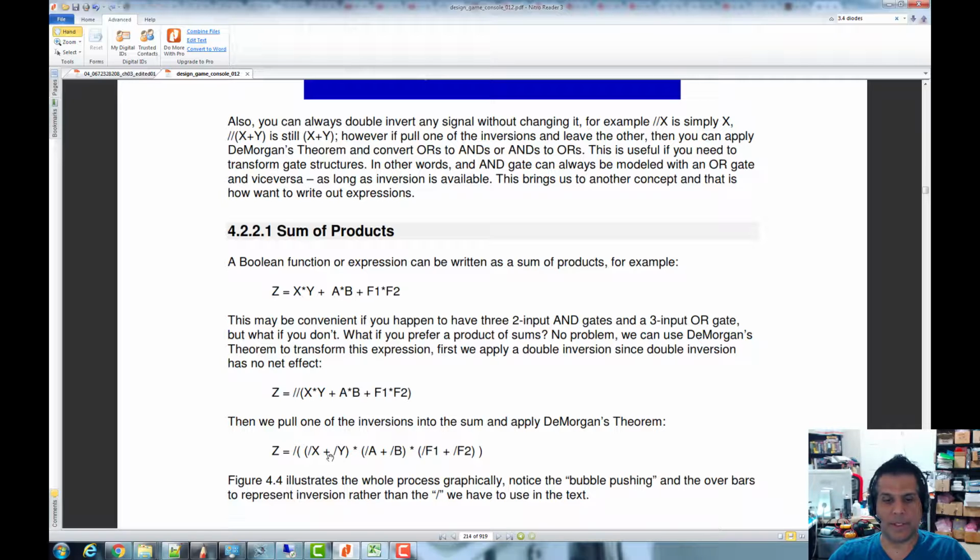So let's say, for example, we have a 3-input AND gate. So this would be one expression here, one expression here, one expression here. Each one of these, we've got to AND this, and then we need one OR gate here, one OR gate here, one OR gate here, and then we would have a bunch of inverters, then invert the whole thing, and it would be equivalent to this. So the whole point is you can transform logic using these rules into different forms that might be easier for you to implement with the gates that you have, all right?